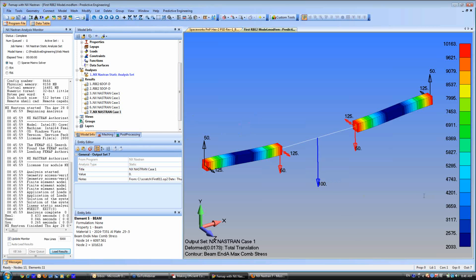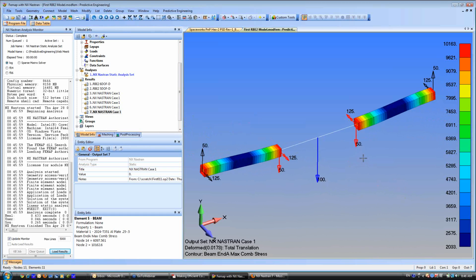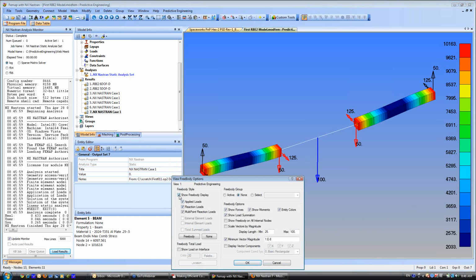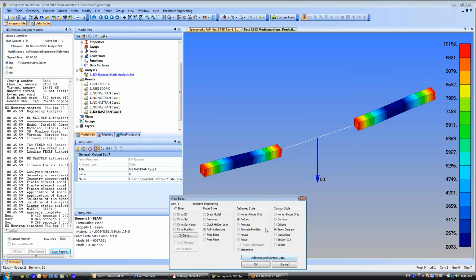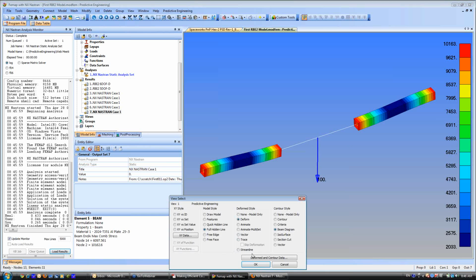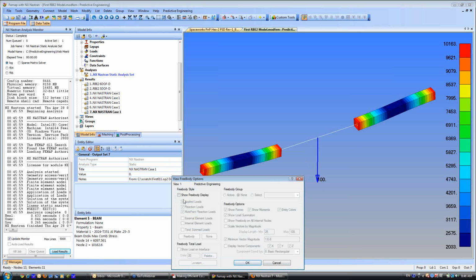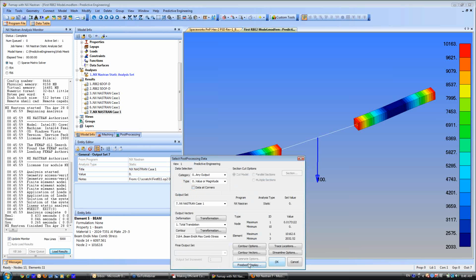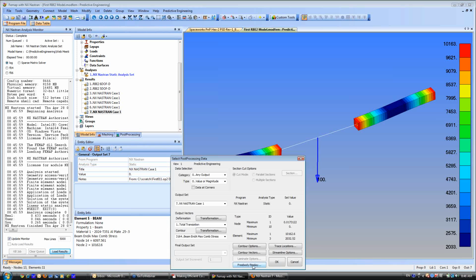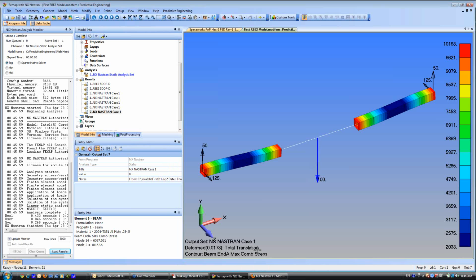Nice having this simple model. Runs fast, goes quick. Okay. On the free body diagram, what you're seeing here, in the default, of course, you don't see that. There's none. There's our load, 100 pounds. Free body, let's show it. Let's only look at reaction loads. I hope I'm not going too fast on that. You saw it. Show free body, reaction loads. That's going to be at your constraints. You can get that as a default.